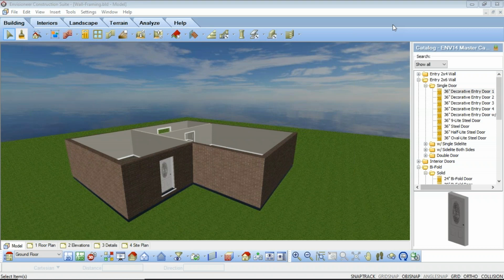You can select the framing member that you want to use for your walls. You can also customize the framing settings for each building location in your project. You can define custom framing settings for individual walls, openings, and intersections by going into the framing mode.